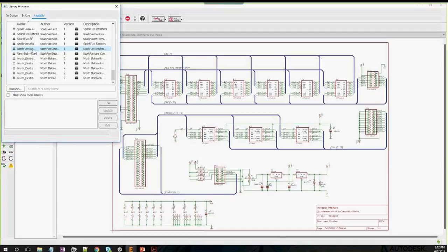There's a question here. Is there a way in Eagle to make pads on the middle layer when designing? Oh, no. No, not yet. Currently we don't have any mechanism for making pads on internal layers. You can fake it. You can work around it using the layers and drawing certain features, but you have to do it manually. There's nothing nicely integrated to support that workflow for inner layer components.